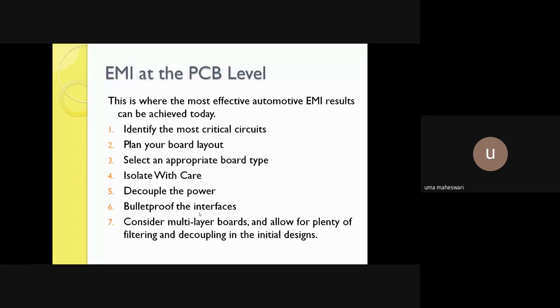So the first one is the most important one, that is identification of the most critical circuits of the schematic of your product. Then plan your board layout well, and an appropriate board type has to be selected. Isolate with care, and decoupling of the power side, and bulletproof the interfaces, and consider multi-layer boards, and allow for plenty of filtering and decoupling in initial designs. This way approximately 80% of the problems will be solved.